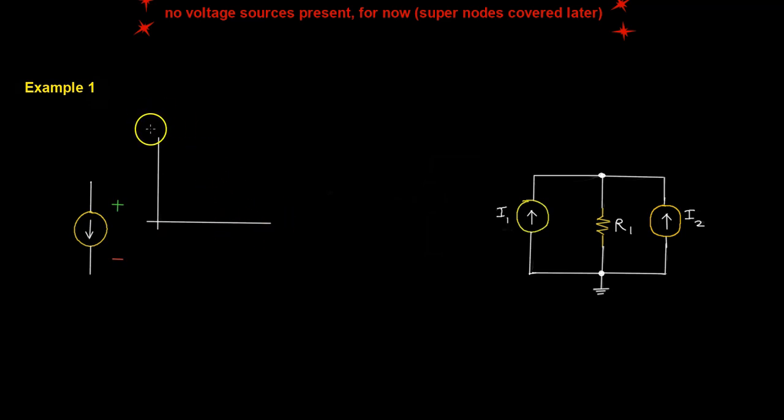Usually for transistors and those kinds of analog design, you'll see current in the vertical axis. So I'll say I here and V here. What you would expect an ideal current source to do is to provide you a particular current no matter what the voltage across it is. You can see it's flat over voltage. In reality, this is not practical.